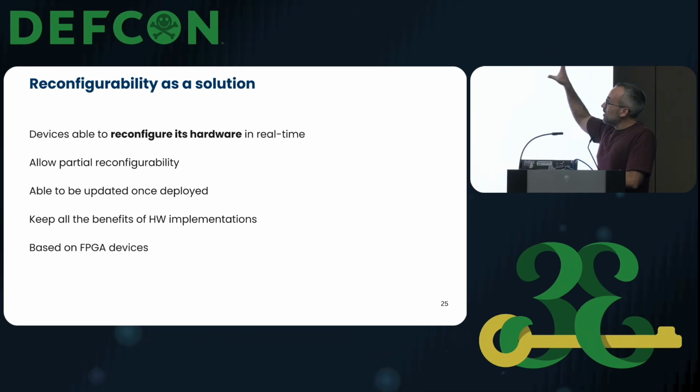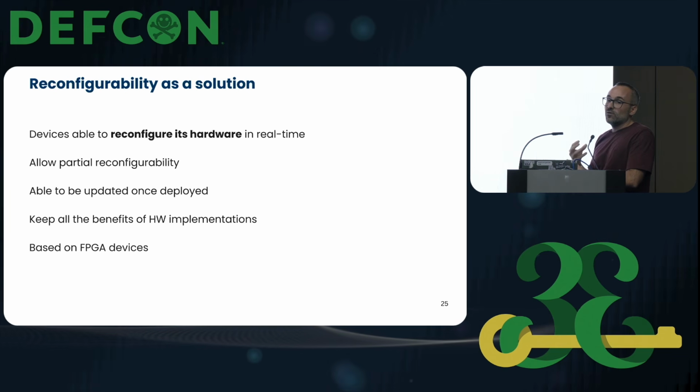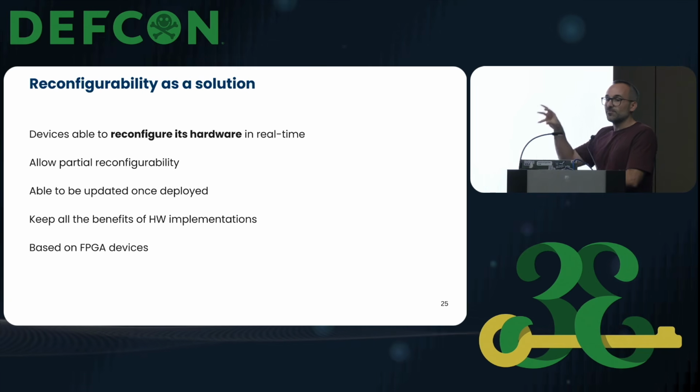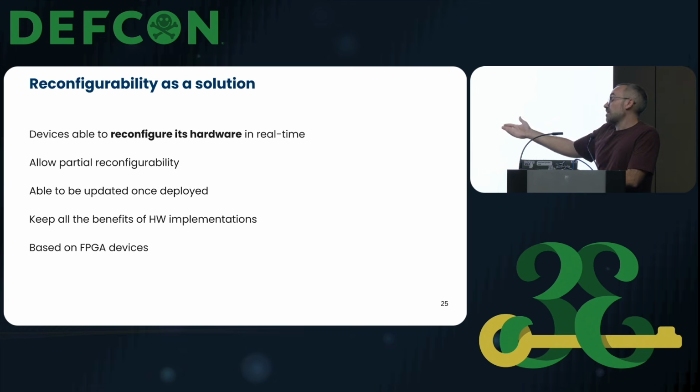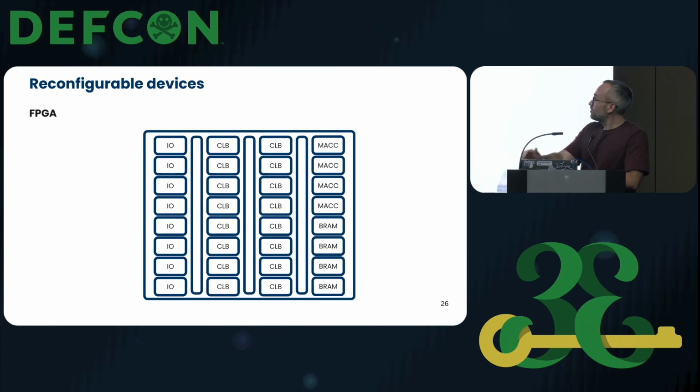So what I propose is to use reconfigurable devices. They are devices that are able to reconfigure their internal hardware. And by reconfiguration, I am not talking about reprogrammability. I am talking about redoing their internal hardware. They also allow partial reconfiguration. We can update only a part of the integrated circuit, and they will keep all the benefits of the hardware implementations. They can be based on FPGAs or other devices, but mostly on FPGAs.